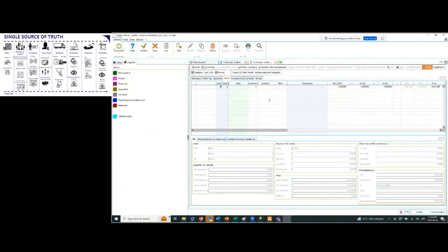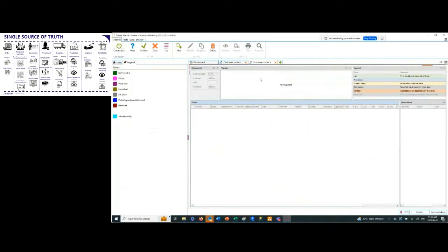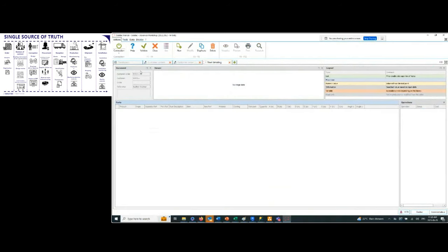And here, if you wanted to create a detailed part, you can actually do it within the platform as well. So if I wanted to add a steel part manually and avoid, if it's a smaller project, for example, and it's just a replacement part, a plate or a bar element for an existing project, you can add a steel part manually here. So I'll just give an example of adding a W shape, a bar element, but apply additional features to it, such as copes, cuts, holes, whatever the case is. So in terms of UI, I'm first starting off by adding a bar element. So here I would select my profile type, okay?